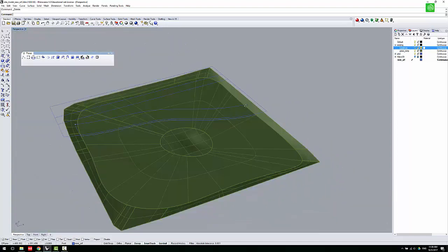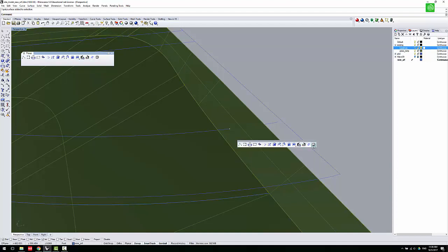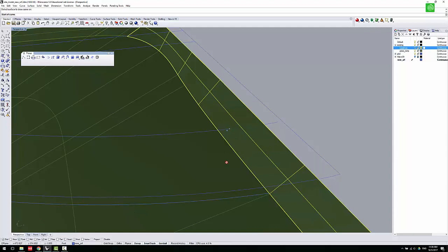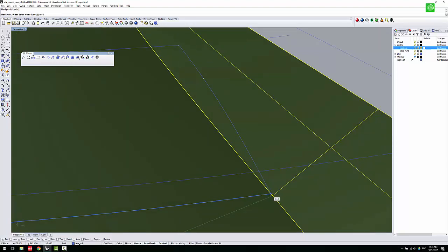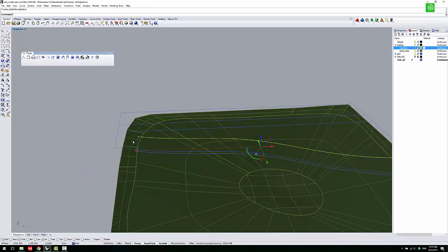The same thing here, we just use interpolate on surface, select this surface, and then we can start drawing. Make sure you check the point, snap, and just draw it. And make sure you snap this point and hit enter. Okay, and the same thing, we need to cut this line. Go to the split tool, select this object to split, hit enter, and select this cutting object, hit enter, and they will have 2 pieces. Okay, once you have these 4 curves, you're great.